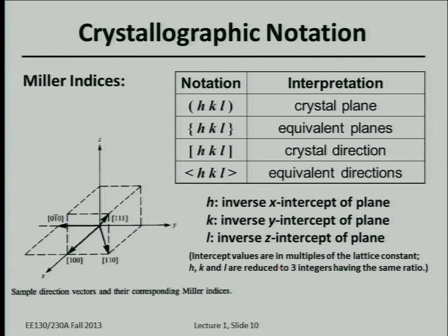Okay, so did anybody notice something weird about the edge of this wafer? It had a notch, exactly. So the notch here is so that during the fabrication process, when the wafer is inserted into a piece of equipment to define the layout orientation of the transistor, it will orient the wafer exactly right so that the transistor will be laid out in a direction to maximize the mobility of the electrons. Okay, so it is important.